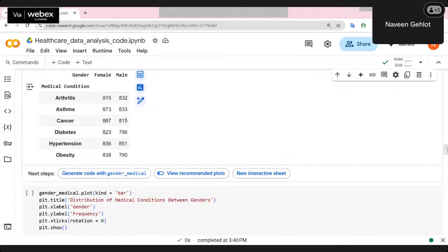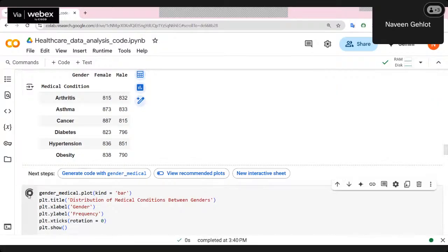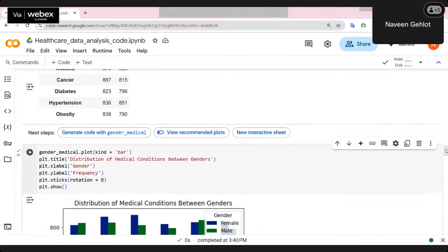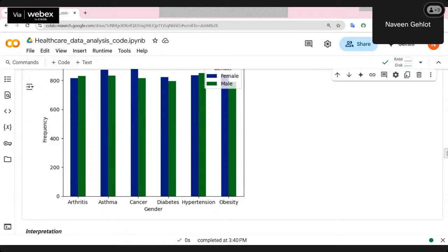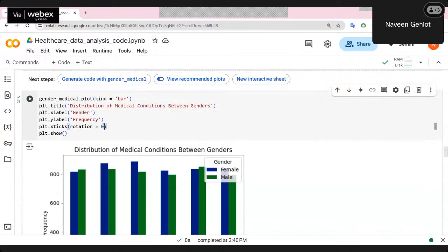So that's your stats. You get the plot with the bar, where there is a partner and the tick marks with the available items that you are interested in. If your data needs some rotation, just put it here. How much you are rotating your text, like 50, 40, 90, 70, whatever you want, you can just put it here.